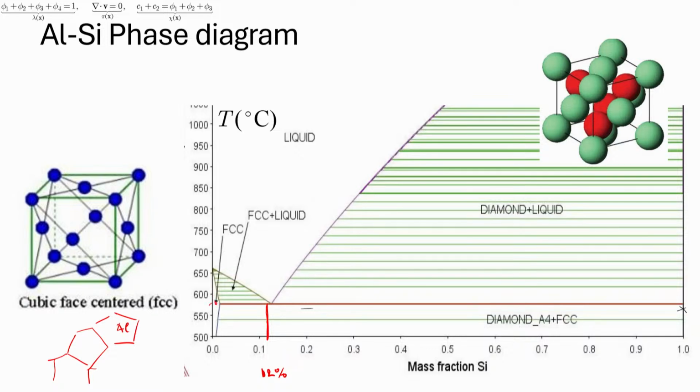So this is this phase, and you have lamellas, or maybe near spherical particles on triple junctions like here, or grain boundaries, right? Much less silicon, of course. That's this phase here, right? You have a mix of silicon and aluminum phase, and then you start heating, right?